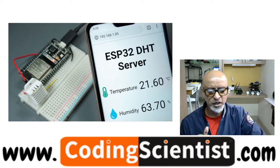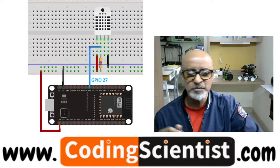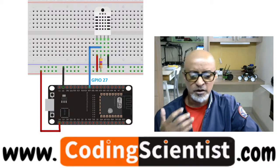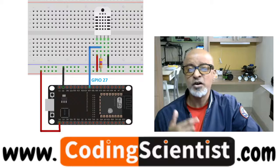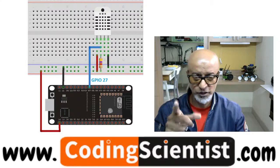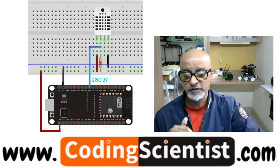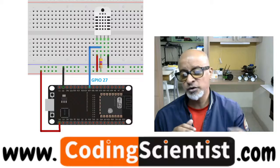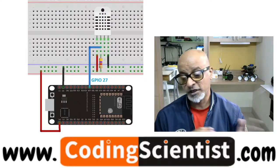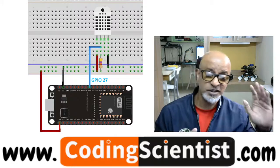Now let's take a look at it from the circuit point of view. It's a pretty simple, straightforward circuit. It's not complex. You need to wire the DHT11 or DHT22 sensor to the ESP32, as I showed, as you can see behind me. In this particular lesson, we are connecting the data pin to GPIO 27 of the ESP32. But you can connect it to any other digital pin, guys. I am leaving it to you, but you'll have to change it in the C++ code.